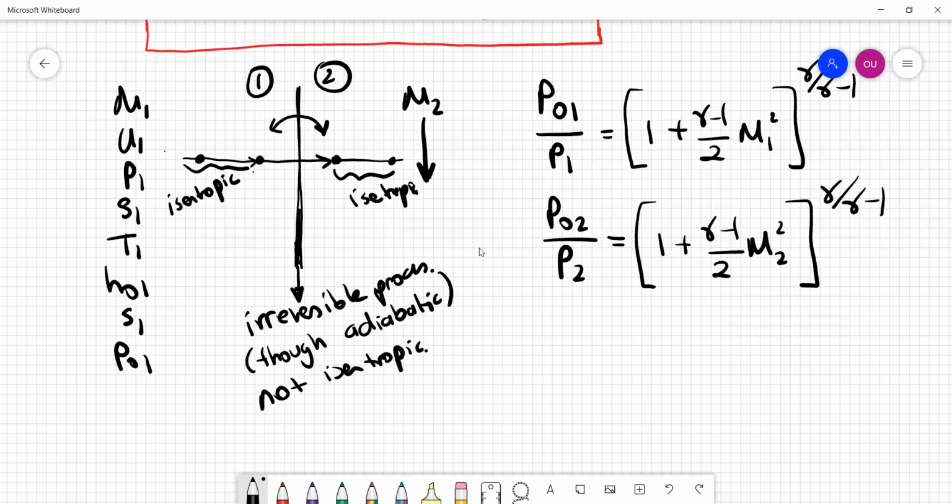Okay, the shock wave itself, as we have discussed in the very beginning, is a very thin layer in the flow field, in the airflow, with very high viscous losses. So there's lots of friction involved, lots of viscous effects involved. So it's not a reversible process because of this physical fact. It is adiabatic though. There is no external Q dot or anything that is incoming.